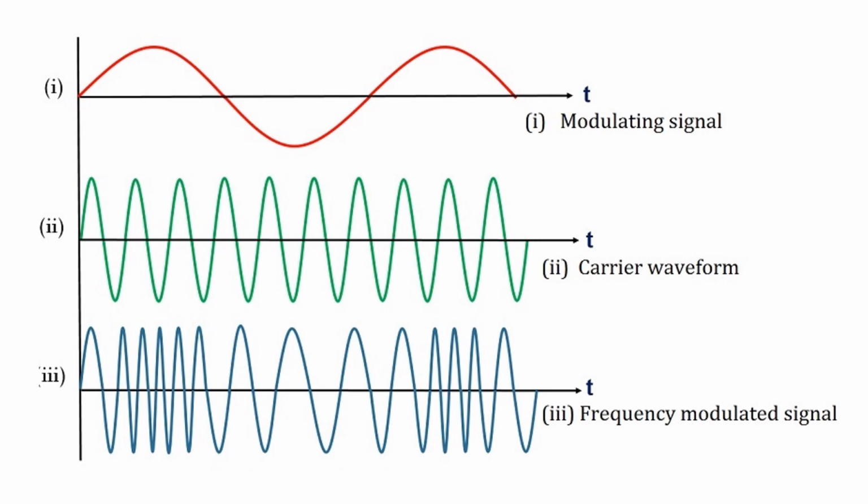So as mentioned earlier, in the FM receiver the detector, which uses the phase discrimination method, compares the phase of the locally generated carrier and the input FM signal, which gives us an amplitude variable signal.